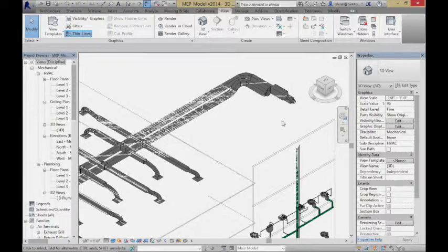Okay. You have to keep the system in balance, because if it gets out of balance, you have that situation where if too much air is blowing into the room and you're not returning it, either the doors blow open, okay, or you have the situation where if the door pulls in, you actually have to pull really hard because it's sort of blown up against the jamb. Okay. Same thing happens if there's too much return but not enough supply, and you have negative pressure. It would suck the door open all the time or something like that. You need to keep those two systems in balance.